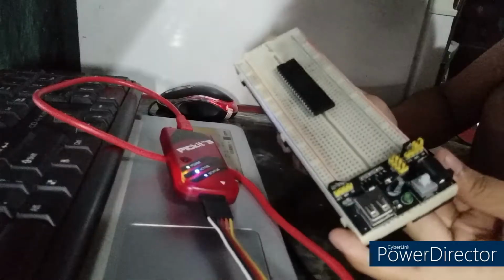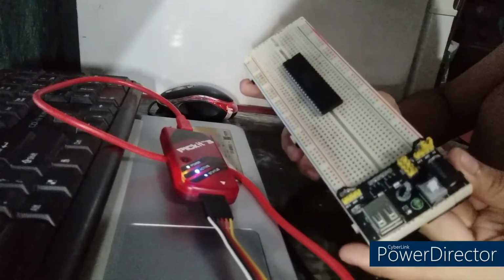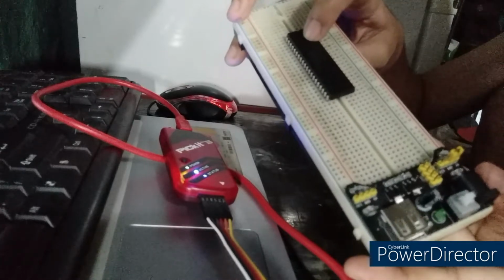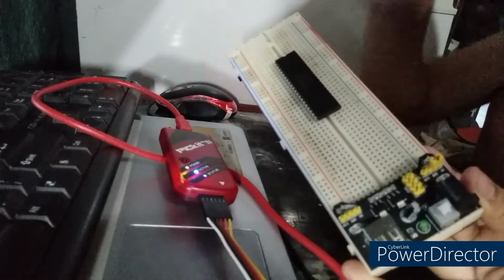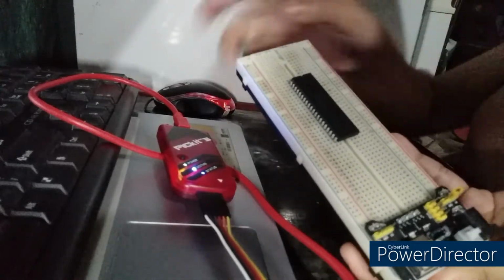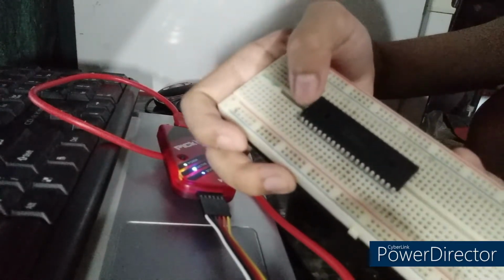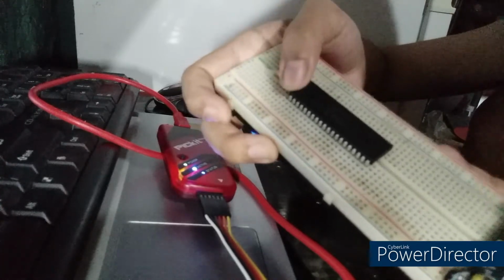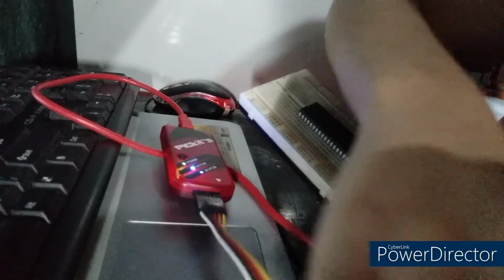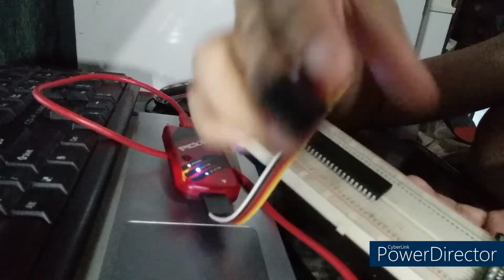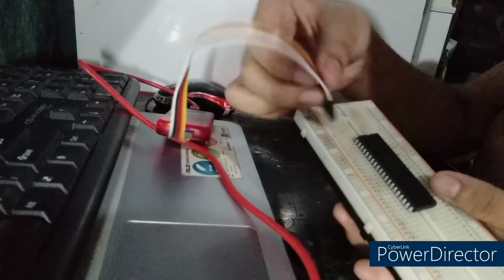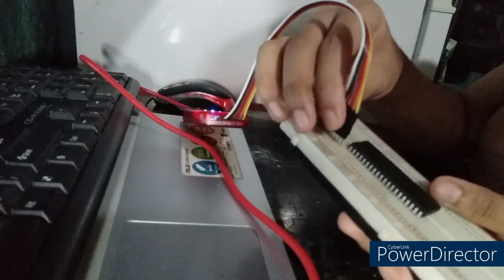It's really important. Now this time we will be connecting our PICkit 3 to our programmable IC, the PIC16F18875 IC here on the breadboard. You have to take note that this IC has 40 pins, and you have to take note of the notch here on our IC, which is our mark for the first pin. We will connect the PICkit 3 pin number 1, which is the yellow wire here, to our pin number 1. Okay, so let's just connect our PICkit 3 here on our breadboard first. So let's connect it here.